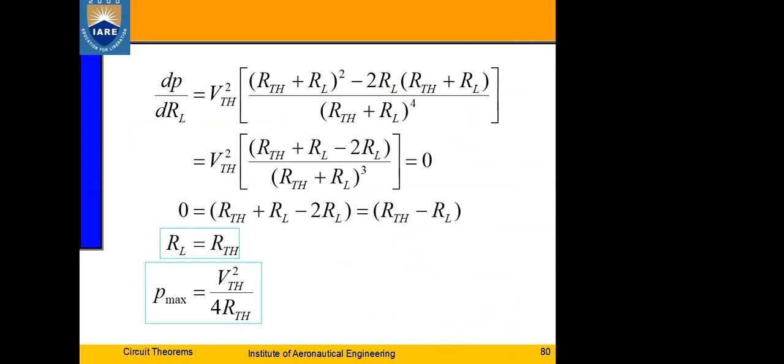Now connect this I to the display, so that these two components together give you the ammeter. This ammeter has a positive terminal and a negative terminal. In the circuit, the positive terminal is connected with the voltage source and the negative terminal is connected with the resistor. So connect this positive terminal, and the negative terminal to the resistor.